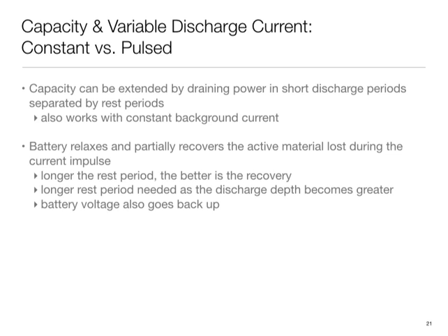Last question? Yeah. Does this rejuvenation happen at any discharge current? No, rejuvenation will manifest itself when your current was high enough to begin to cause that depletion. If you are drawing continual current at a very low level, then the battery will not even see the effect. So the current has to be larger for this to manifest.